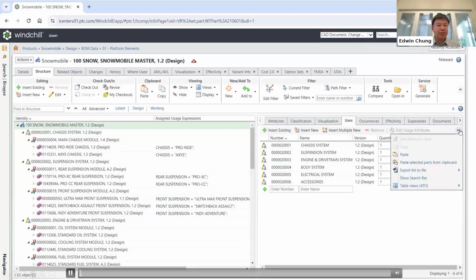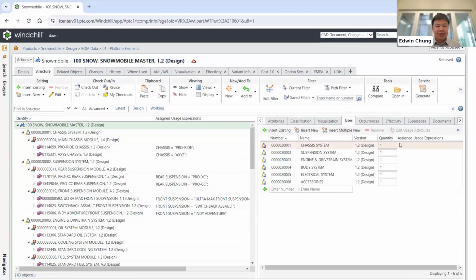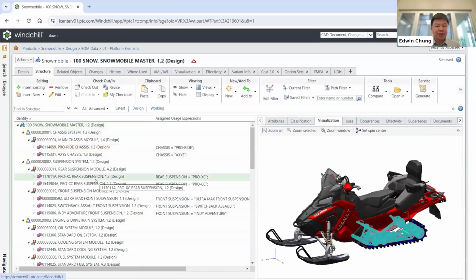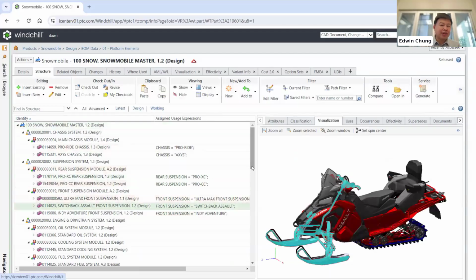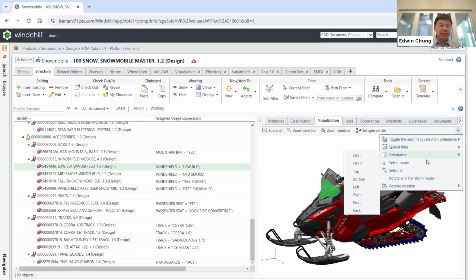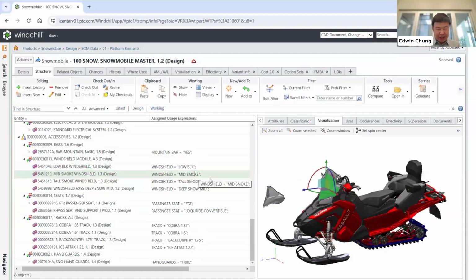That sounds great, Michael. Yeah, so you could think of Windchill and Creo as one system, right? The mechanical engineers are designing in Creo and saving directly, quote unquote, to Windchill so that every file is versioned, numbered, and related to the right part. From the workspace, you can see who has the model checked out, the lifecycle state, for example, in work, under review, released, and whether downstream teams or suppliers can use that file. As designs evolve, Windchill creates iterations for every save and revisions for formal releases, which can be numbers or letters as we configure it, so we get traceability without clutter.